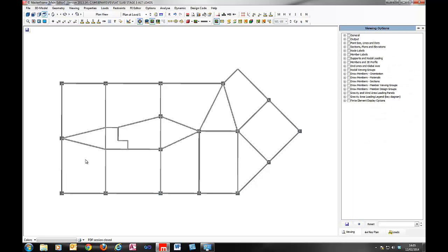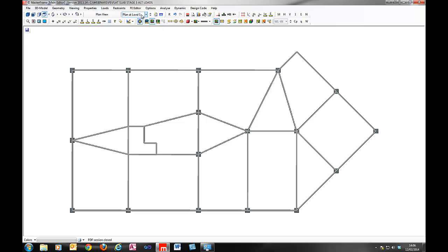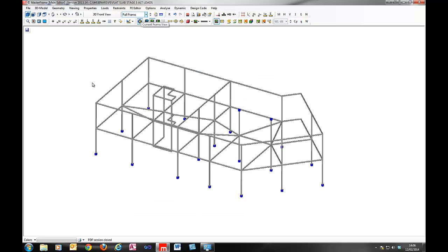And at analysis time, for the load case, for example, where I have load sets 3, 4, and 5 included, it will know that the loads in this area that are DA are now D3. It will attribute the load to the correct load group for the load case it's dealing with. And in your analysis, you will see that reflected in your deflections and in your results. And that's essentially how patterned loading is handled.